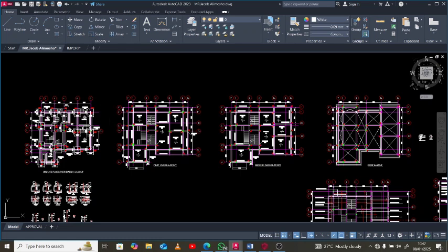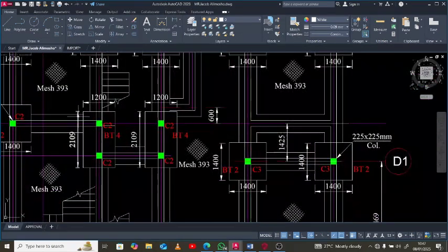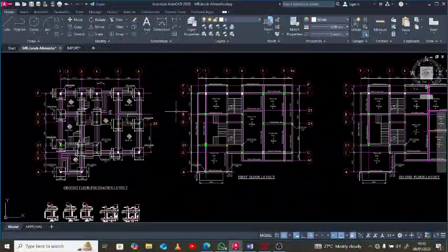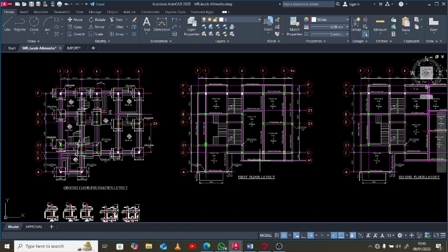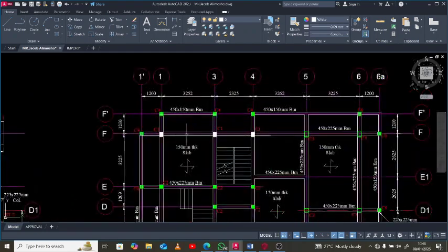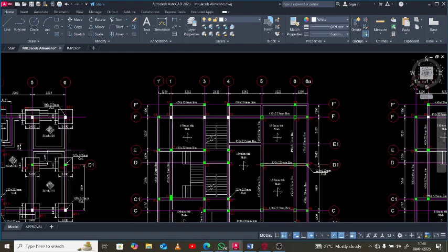This was produced from the architectural drawing. Looking at this, the pad and strip foundation was adopted. We have cantilevers around the sides of the first floor, cantilevering from grid line 1, grid line F, grid line C. Anything outside grid line F up there is a cantilever.